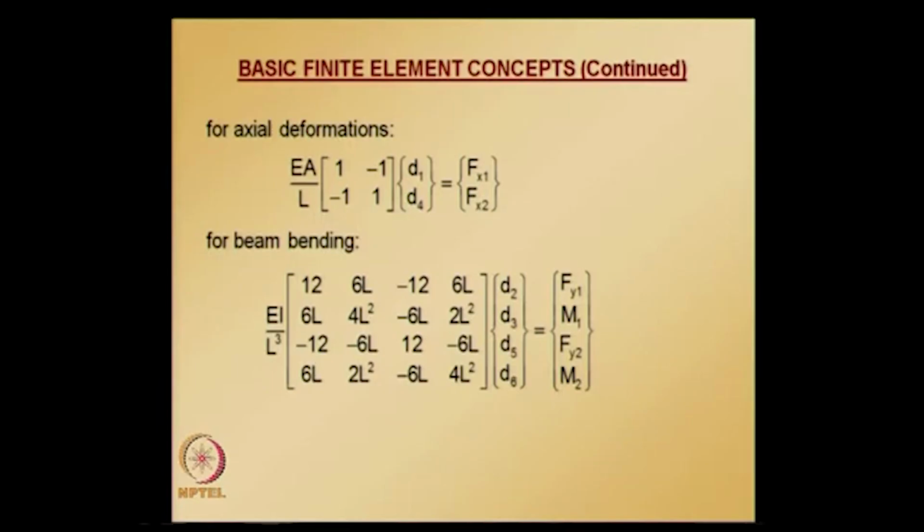The complete equation for a planar frame element in the local coordinate system is simply a combination of these two sets of equations, that is, the element equations corresponding to axial deformation and the element equations corresponding to beam bending.